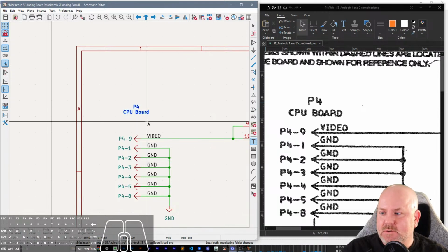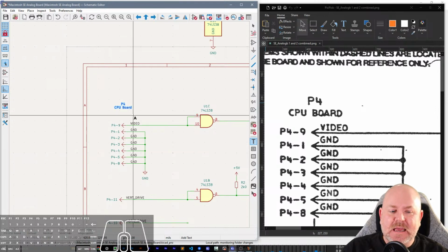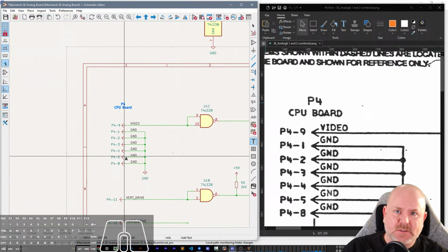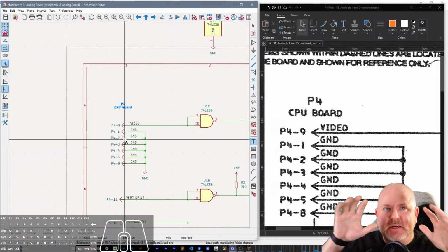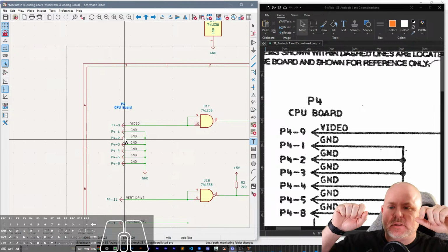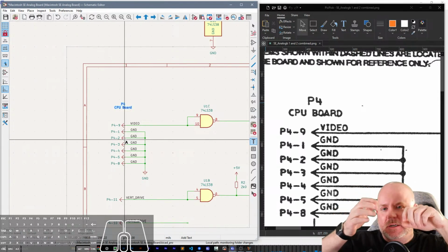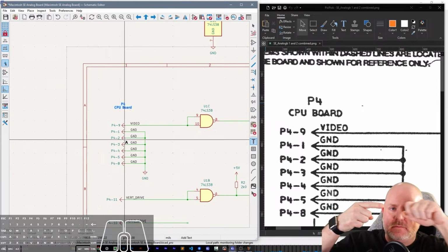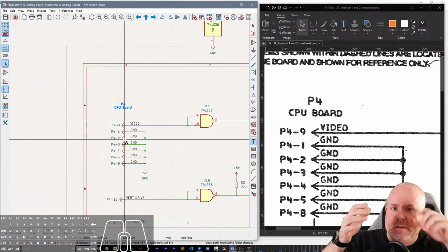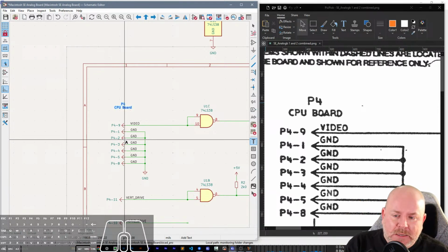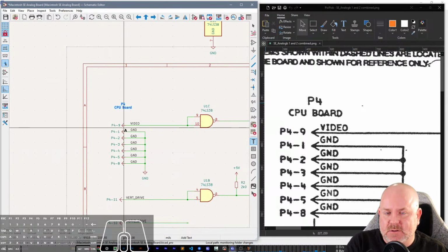In this, so Hardfeld, are you setting all the symbols to passive? No. In this connector, these are set to passive because these are meant to indicate an off-board connector, which in a CRT, it's really common to see these, where they look like heavy-duty DuPont or header pin connections. There's a piece of metal and then something gets shoved onto it. It's really built that way for repairability, so you can disconnect the high voltage stuff and pull it out.